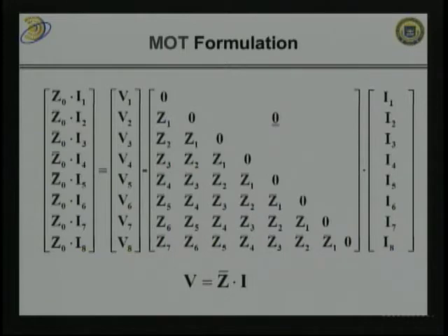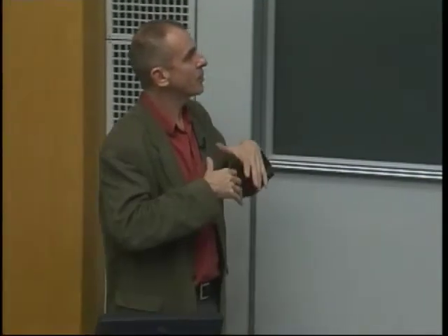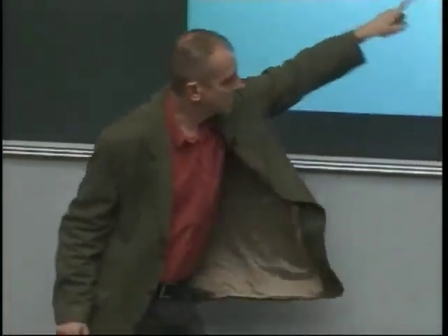That's how this thing works. It's somewhat similar to, say, the FDTD, finite difference time domain, or finite element time domain solvers that some of you may be familiar with. It's different in the sense that we don't solve for fields around the object. No, I solve for currents on the object. Okay? And these currents propagate through space at the speed of light, characterized by Green's functions. That's it. All right. Okay, these equations here, I can also write them in this form here.